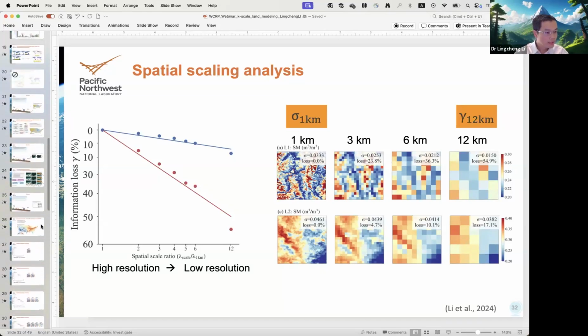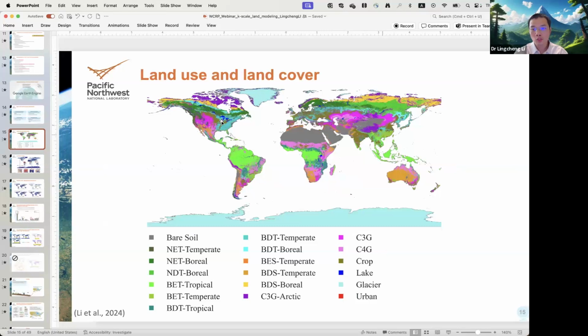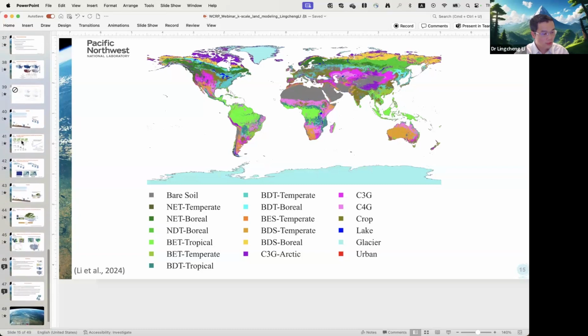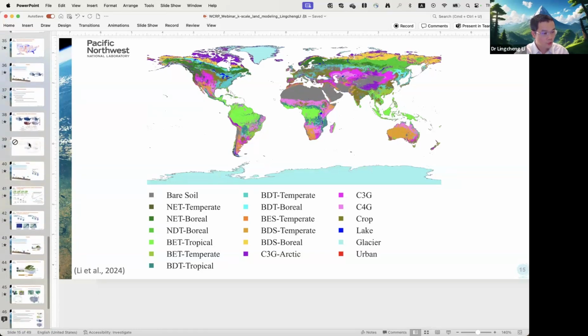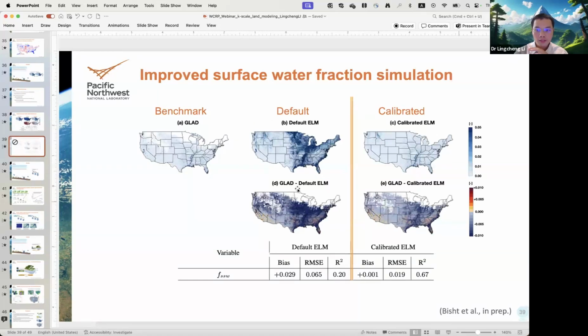If you are talking about the land cover for the water surface, for example the lake, because our data source is based on models, it will update the water cover each year. And if you want more detailed data, you can refer to the global surface water data set, which I remember is at 30 meters. If your question is related to the calibration, in the calibration we mentioned the water surface fractions. We calibrate because the model itself can simulate the water surface, and we can consider the time variabilities in the calibration or the objective functions.